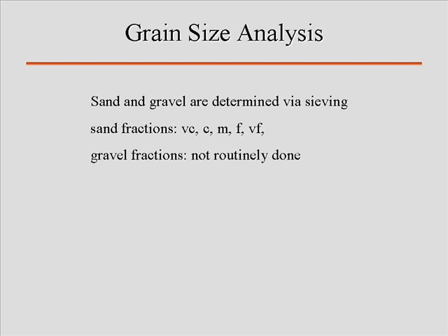Now, I talked about the idea that there's two methods for this. The real hassle with the pipette sieve method, which kind of sucks, is that if you're going to be extracting a physical sample, you've got to weigh it. You're weighing something that is in a fluid. You've got to get rid of the fluid. You've got to make this as fast as possible.